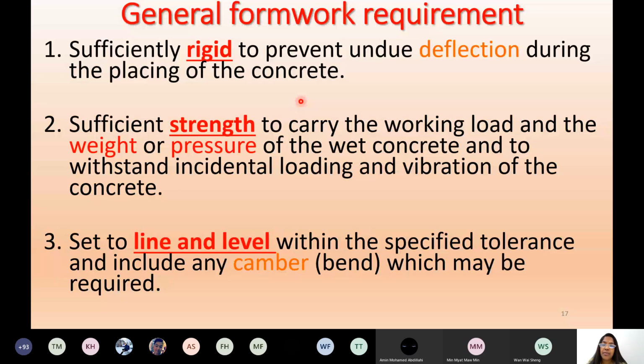Yes, for slab, is it the same? A month. It depends, but nowadays they are having quick setting cement with quick setting cement admixtures. It can be reduced, but generally speaking, slabs will go for one month, and columns, beams, all the other concreting work will be there for 14 days curing. And the formwork removal slightly follows this, but I will tell you the sequence of removing the formwork. I will explain after this. So there is a sequence in line with the concreting.